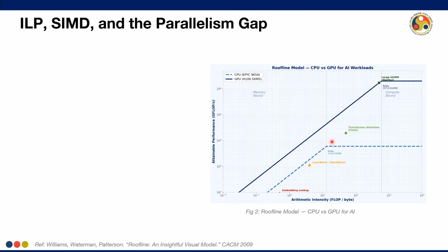So here this is the peak performance curve, and here is the peak memory bandwidth curve, which is the slope that you are seeing here. This straight line is essentially your peak performance, and where it collides, this intersection point decides which workloads are memory bound, which is the left hand side of this intersection, and on the right hand side we will get the compute intensive workloads, right?